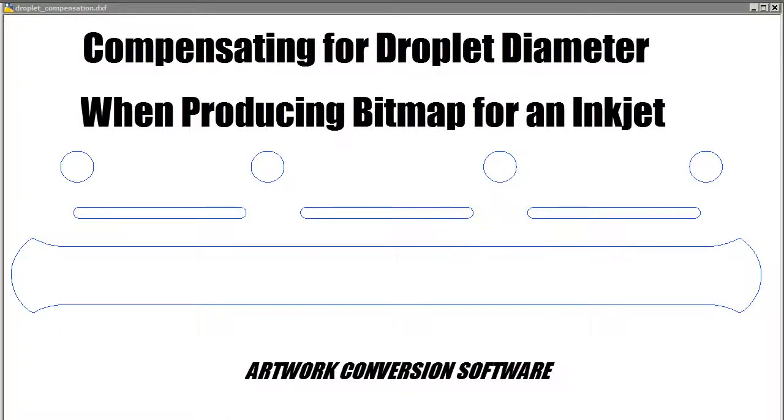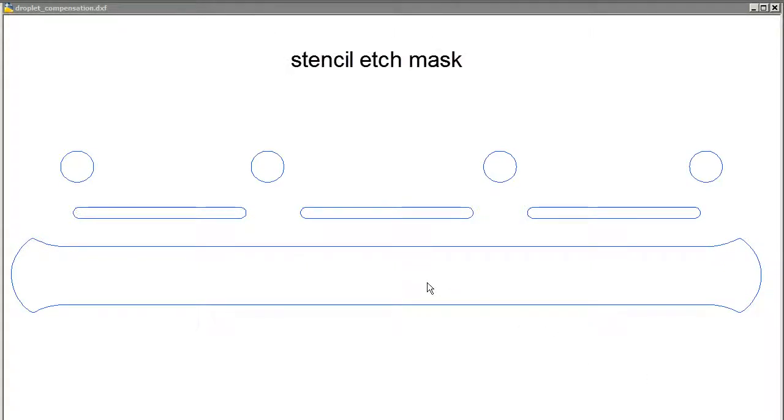Good afternoon. In part 2 of this tutorial, I'm going to talk about what one needs to do to compensate for the diameter of the inkjet droplet. If you recall, we had a stencil, and the stencil had three different opening shapes: this circle, this narrow slot, and this larger slot. The most critical dimension would be the width of this slot, which we measured to be 0.079 millimeter. That's what we want to get onto our substrate.